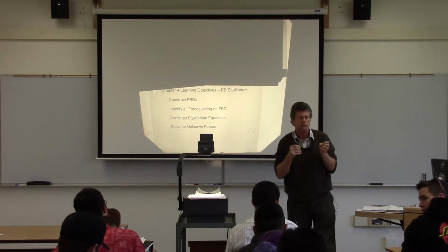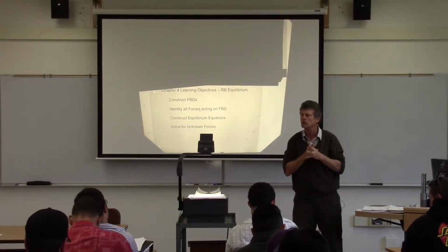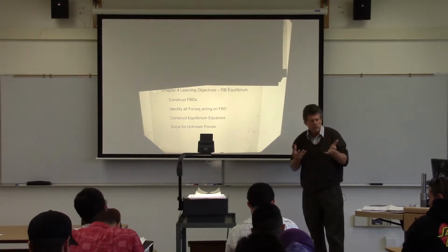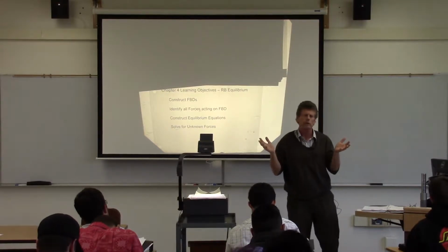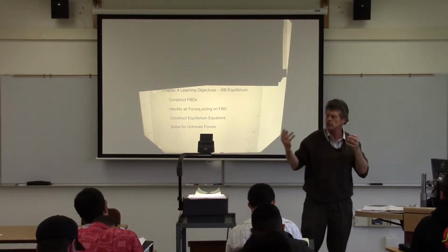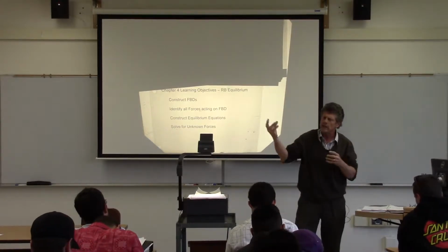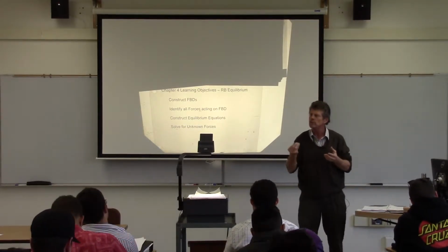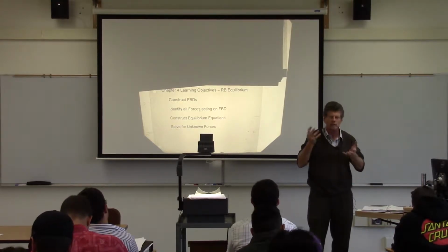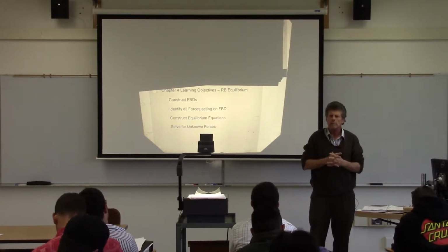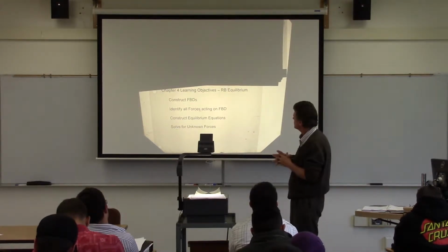When you get into structural analysis, whether you're mechanical or civil, you will be using statics as a kind of grounding to see whether your numbers are ballpark figures. You might be using complicated approaches like finite elements, but you always want to ground that with something that you know. So you can do some simple calculations with statics to give you an idea of the ballpark of the forces in a particular project.